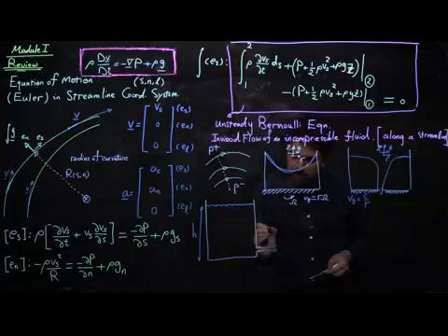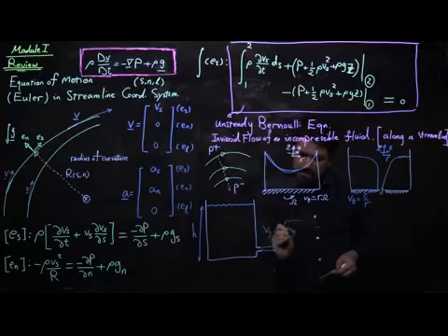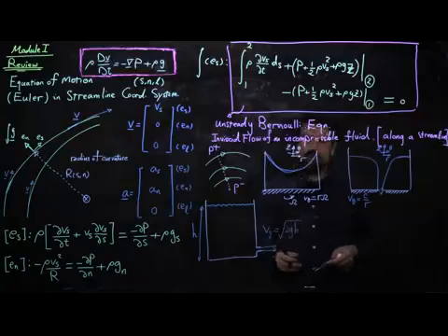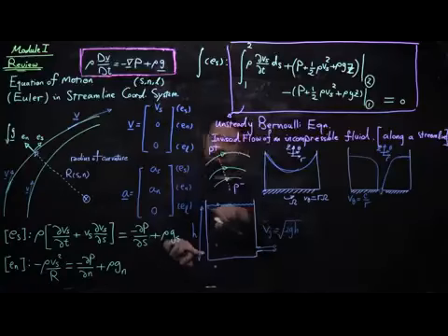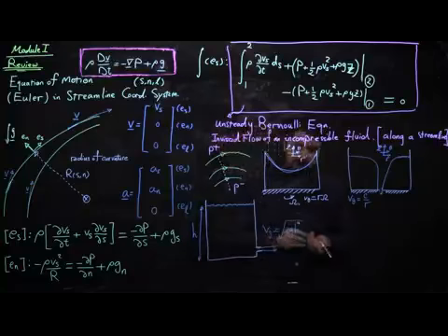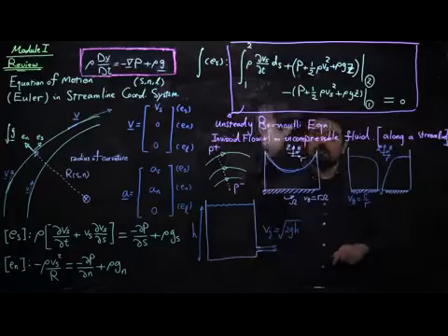We use Bernoulli to show that the velocity of this jet is a result that is known as Torricelli's result, the square root of 2gh, where h is the height of the free surface compared to the orifice. We also saw that this is the steady state case of Bernoulli.